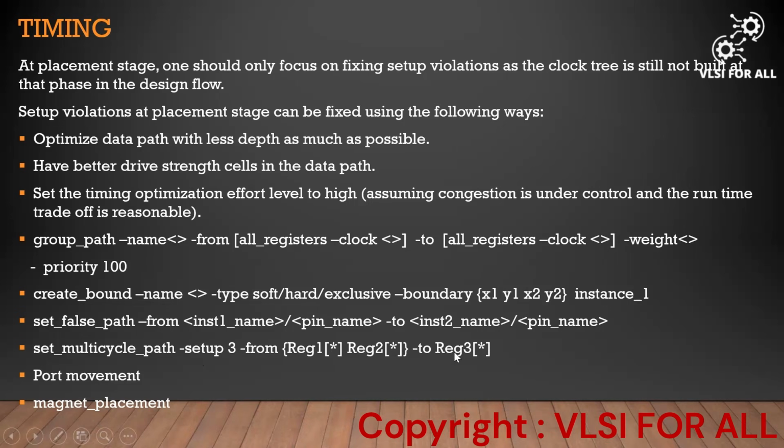hyphen to do that. And if the logic depth is less and it is possible to optimize, like changing the driving strength or VT swapping, this data path optimization will be a benefit for us in fixing the setup timing. So in the data path, we have to make sure we have better drive strength cells and set timing optimization effort level to high. Likewise, as we discussed for congestion, for timing optimization also effort should be high. Then only the timing will get better optimized.